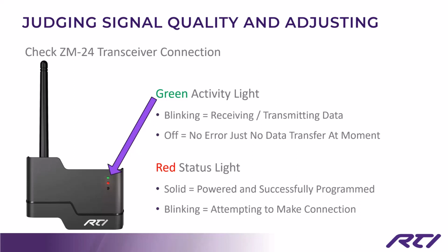If it's off, and this is a question that comes up all the time, people start to go, well, hold on, is it working? Is it not? No, off just means that there's no data transferring at the moment. This is about the activity, right? If it's blinking, that means something's happening. If it's off, there's just no activity right now, and that's okay.